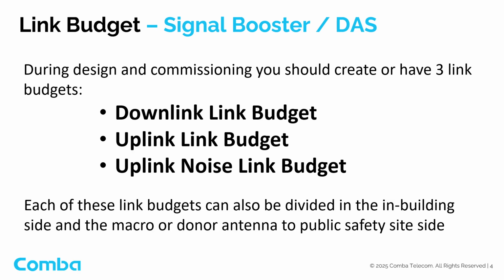Furthermore, the link budget is used to guide the design of the antenna layout of the DAS system, estimating the coverage each antenna will provide. There are many forms of link budgets. Simple link budgets can be performed by hand using formulas or by using calculator tools built in Excel or other programs. The most common link budget softwares that are available are IB-Wave design software and RANPlan design software, which are basically very sophisticated link budget calculators, which can provide a visual coverage heat map of estimated received power levels.